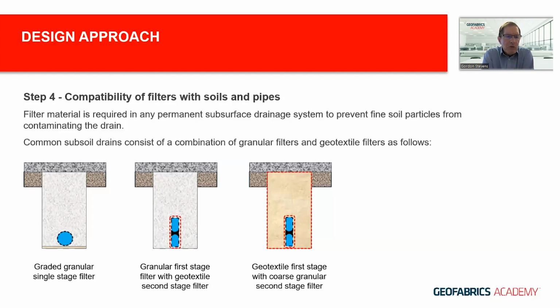The more difficult bits come with the compatibility of the filters with soils and pipes, and this requires a little bit more in-depth calculations around filter criteria. So what we see here is common subsoil drains, which consist of some form of granular filter, with or without geotextiles, and some form of drainage pipe.